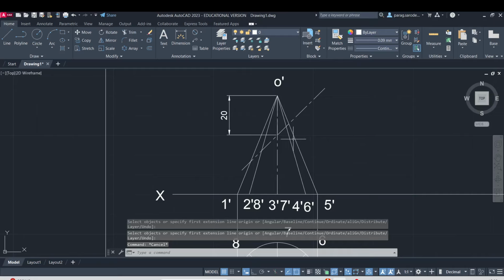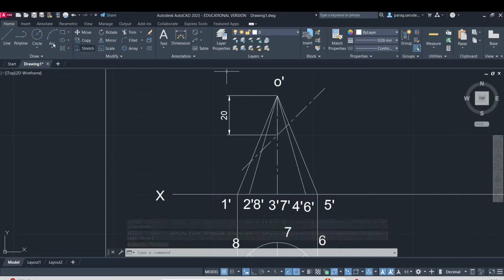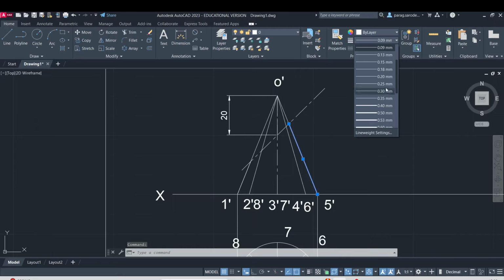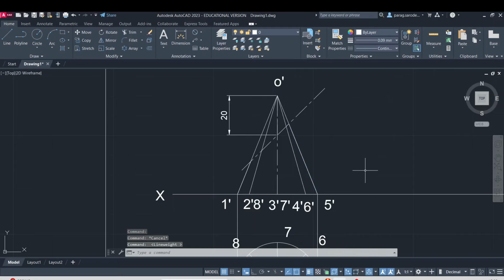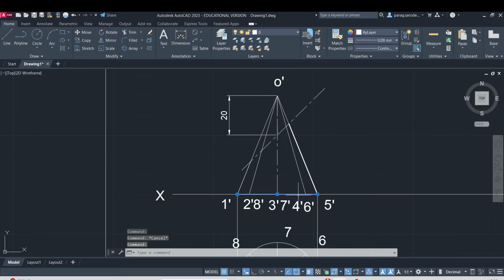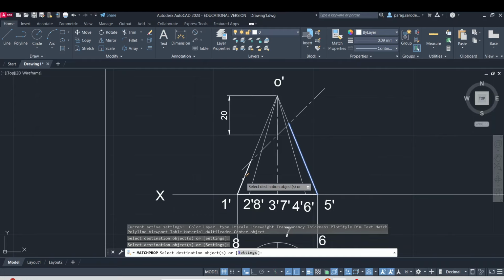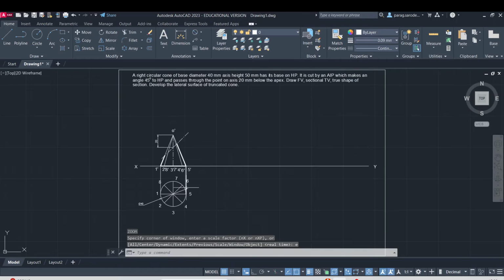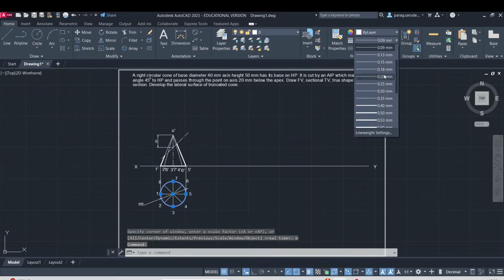Okay. So now this, which is the retained part, we will show by using dark lines. So let us redraw it. Okay, so this is nothing but the retained part. So let us make it thick. Switch on the line weights. See that the base also needs to be thickened. So let us take the mesh properties, base. Okay, then let us click on the zoom again, and this is nothing but the outer part which needs to be made thick again.